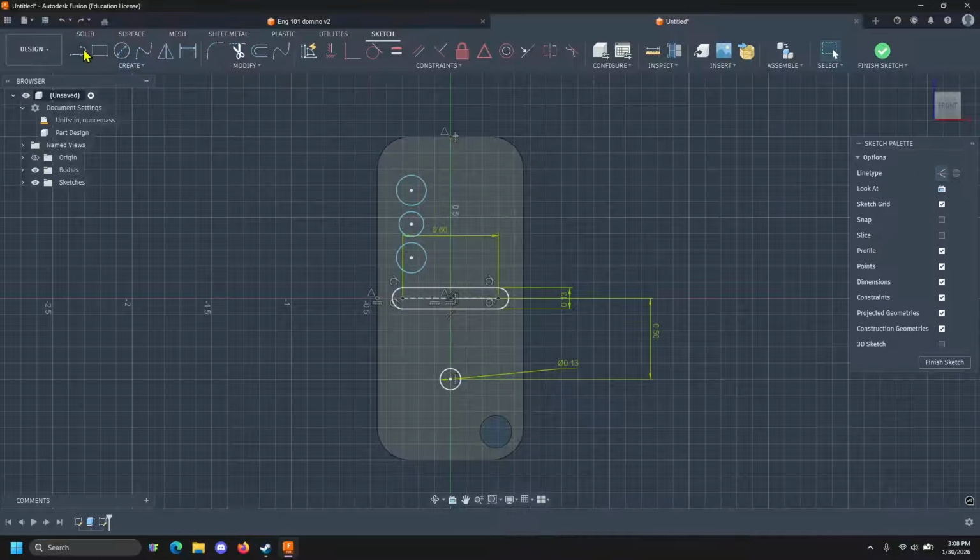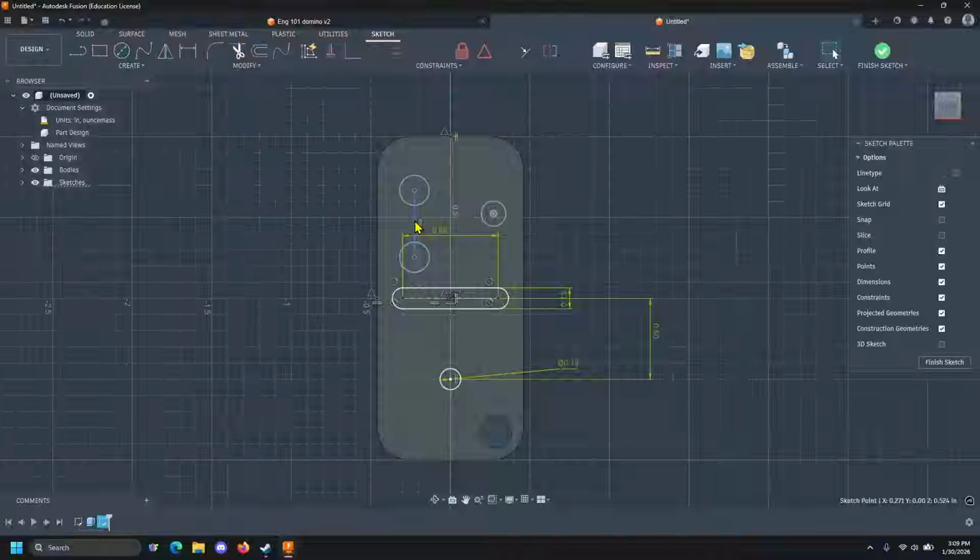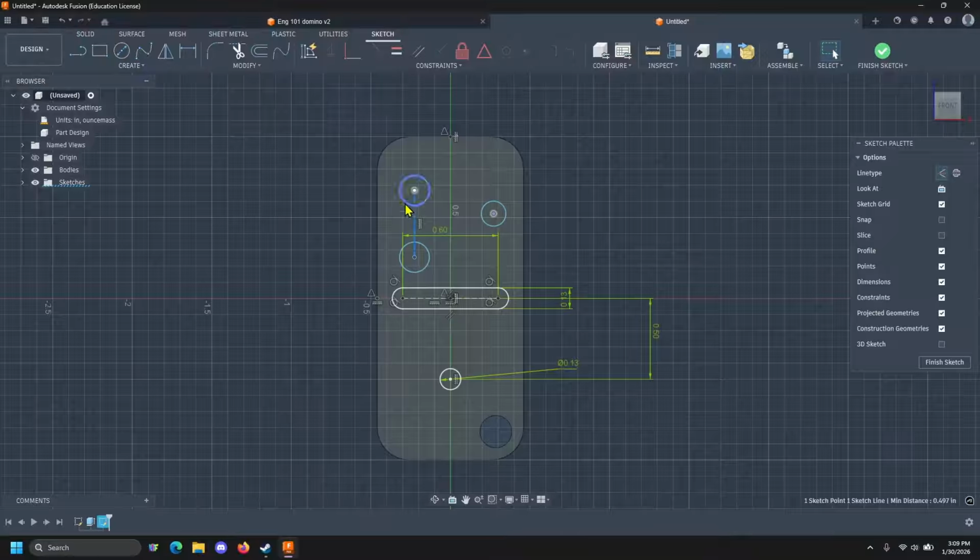So we're going to create these lines, and we're going to do one between the centers of the top and the bottom of our 3 circles that we just placed. Now, this middle one is not tied to those, but these two are tied together now. So we're going to quickly hold shift and click on the center of the 3rd circle that isn't already attached on the line, and we're going to hold shift and click on the construction line, and we're going to choose this triangle option in the constraint. So this is the midpoint constraint.